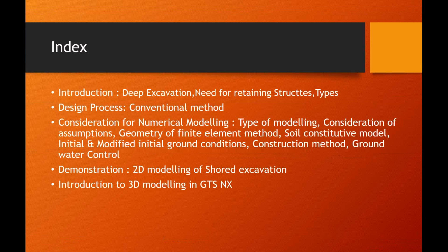So today in this presentation, first of all, we will start with an introduction to deep excavation. What is the need for retaining structures? What are the different types? Design process, what is basically the conventional method? Consideration for numerical modeling, like what type of modeling, consideration of assumption, geometry of finite element method, soil constitutive model, initial and modified initial ground conditions, construction method, groundwater control method, etc. Demonstration will basically take into 3D modeling in GTS NX.